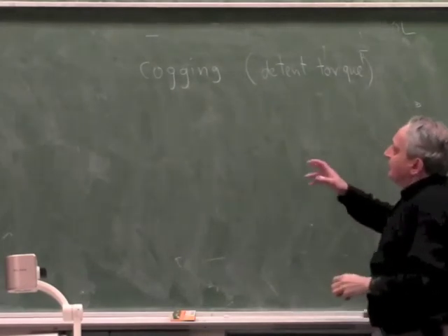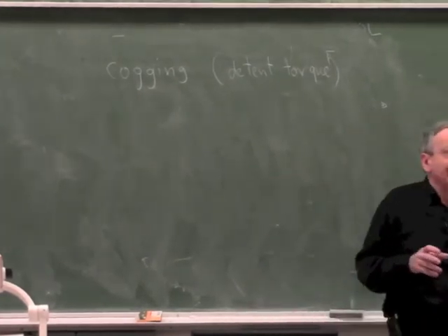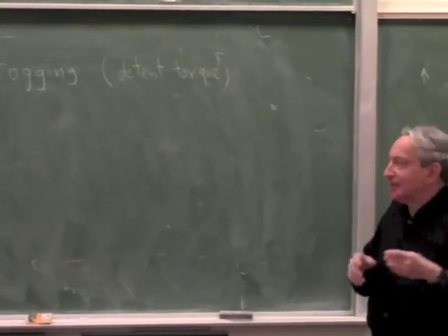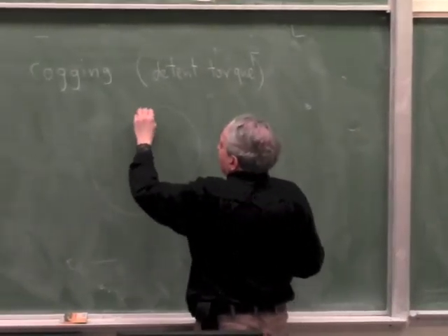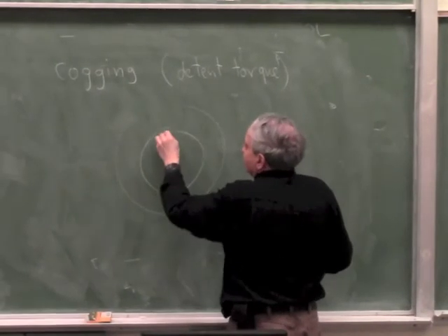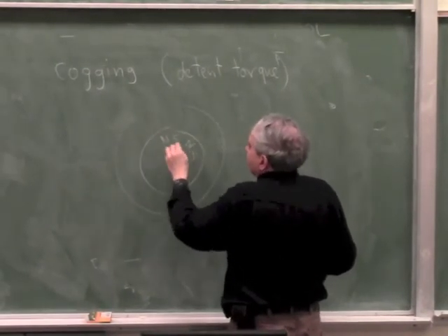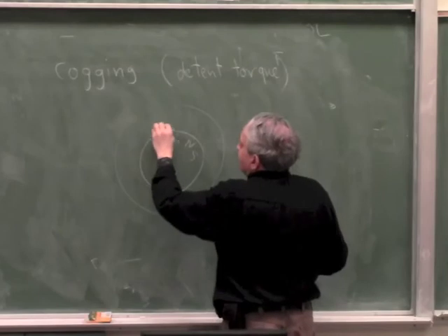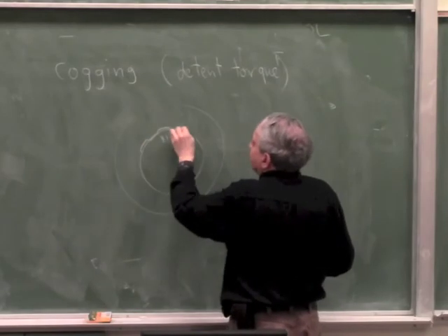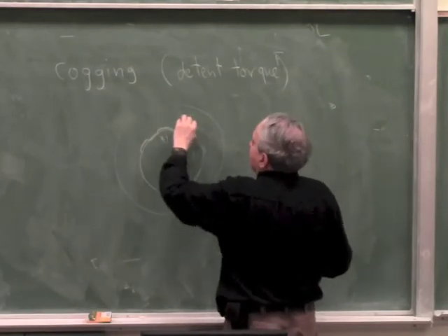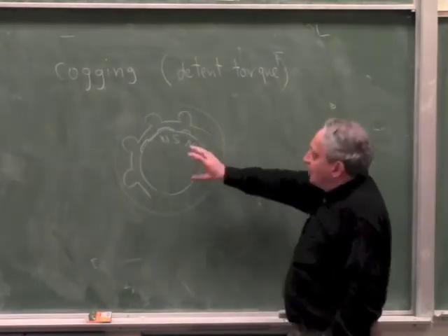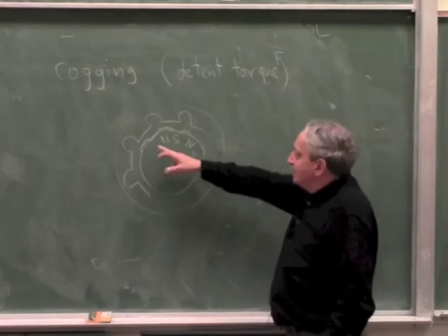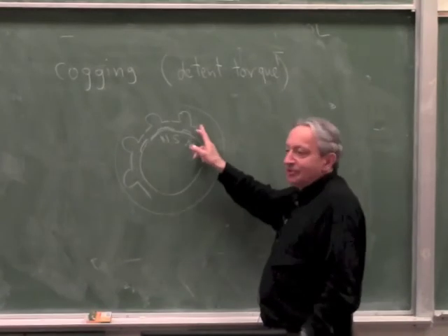Now what this means is that a motor has a natural structure inside. When we talked about a stepper motor, we said it inside has 50 poles and they can be smooth or salient. Salient means sticking out. And then it has a stator which has slots with winding. And I mentioned there is some natural detent position where the magnets like to line up with these salient poles.